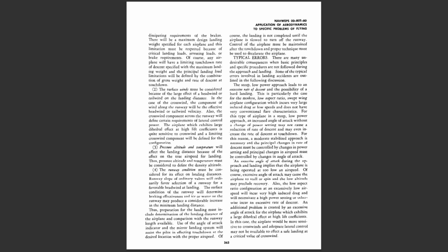An additional problem is created by an excessive angle of attack for the airplane, which exhibits a large dihedral effect at high lift coefficients. In this case, the airplane would be more sensitive to crosswinds, and adequate lateral control may not be available to effect a safe landing at a critical value of crosswind.